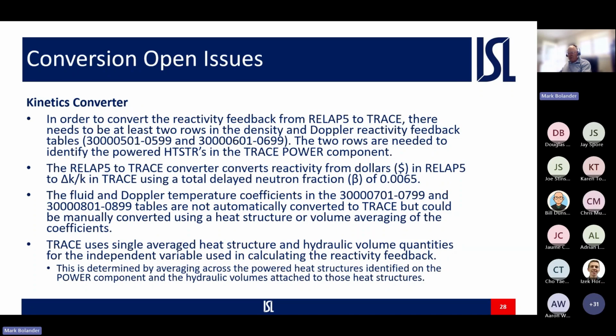We ran across one case, and in fact that's one of the problems in our exercises, where there was just one entry and it didn't convert over properly. The 2 rows are needed in these 2 tables to identify the powered heat structure in the TRACE power component.